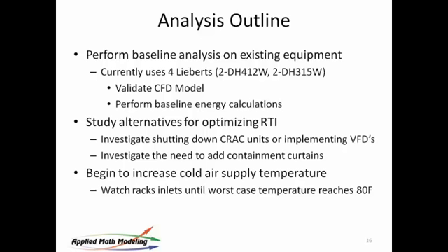What happens if we shut units down? Now, shutting units down is not a panacea, because once you shut a DX unit down, remember there's a hole there and it's going to leak. So you need to be careful of things like backflow, right? Having said that, it's better than the alternative, which is leaving them on. Generally, a rule of thumb is I'm finding that a DX unit like these will generally run $10,000 to $15,000 a year just to leave it on. So you want to turn them off if you have no choice. A better thing to do would be VFDs, which now you can put on some of the newer DX units.